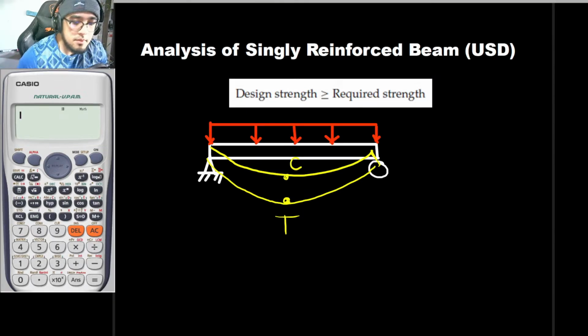And with that, if you can remember from the previous video lecture, we can say that plain concrete is very weak in tension. So once again, it is strong in compression, but relatively weak in tension. And for us to address that issue, as engineers, what we would be doing is placing reinforcing steel bars here so that we would have an adequate tensile strength. So for example, the red ink is to be your rebars, so we will now be placing it at the bottom part for it to resist tension. So that is basically the idea of reinforced beams.